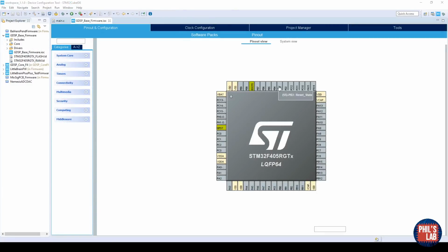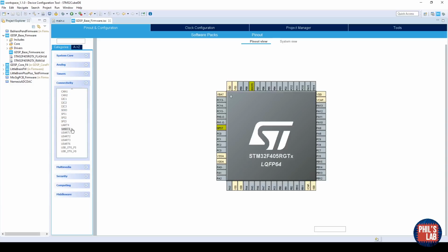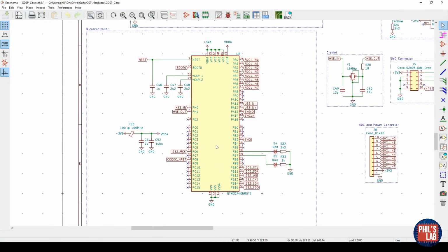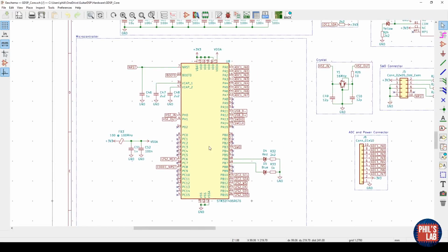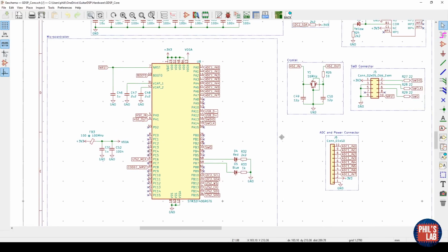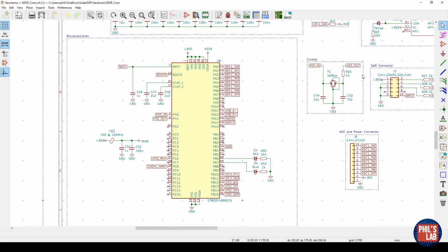device. You can either do that by clicking on certain pins and then choosing what they should be, or you can go on the left here, expand these menu items, and then for example select SPI, UART, and whatever you need. The way we're going to do that is essentially take the pinout from the schematic and then just transfer that over. Most notably, we need to enable serial debug because that'll be our main programming interface with this programming connector over here. We need to enable our crystal and select that this is a 16 MHz crystal.